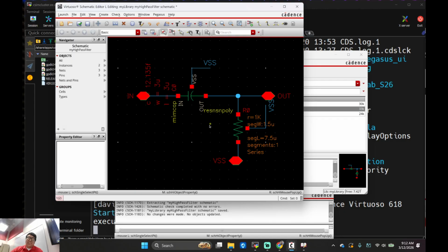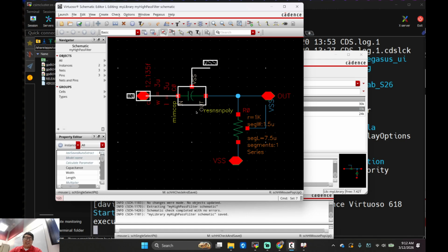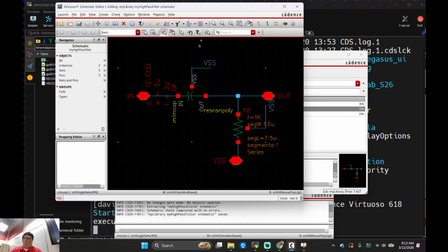So that was something I completely forgot. So these MIM caps, and I wanted to do something cool with them. They're metals. They're not active. They're just pieces of metal with a little insulation between them, but they're good for signals. And I've never worked with a process this small, so I had to make a lot of verification calls, and yes, this is the right way to do it. Anyways, this is a high pass filter.